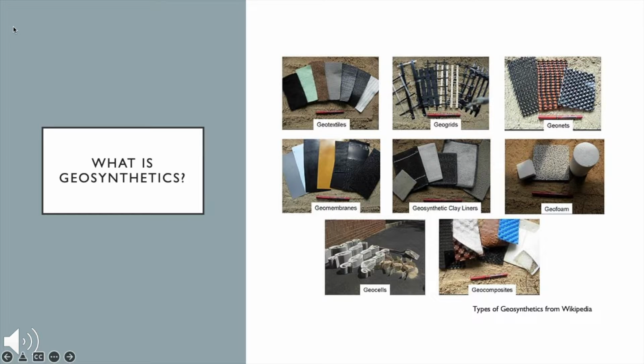So I said before, they all have different functions. For example, geotextiles are permeable fabrics that can separate, filter, protect, or drain when used with soil. Geonets are similar to geogrids, but they're placed in various angles to drain liquids or gases. Geocells, for example, are widely used to control erosion. They stabilize the soil on flat ground along with steep slopes, and they protect channels. So all of them have different functions to use out in the field, but they do have a similar goal.